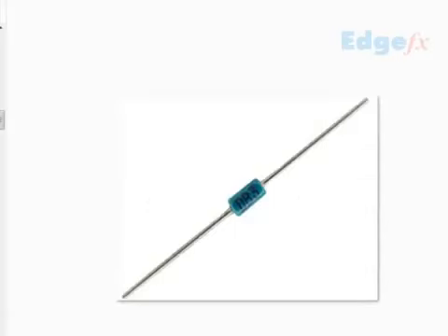The other component is called a DIAC, and the DIAC is a bidirectional device. It conducts in both directions. It looks like a very small tiny component like this. Symbol is like this, and they are always rated with a particular voltage, and if it crosses that voltage only it conducts, like a diode, in both directions.